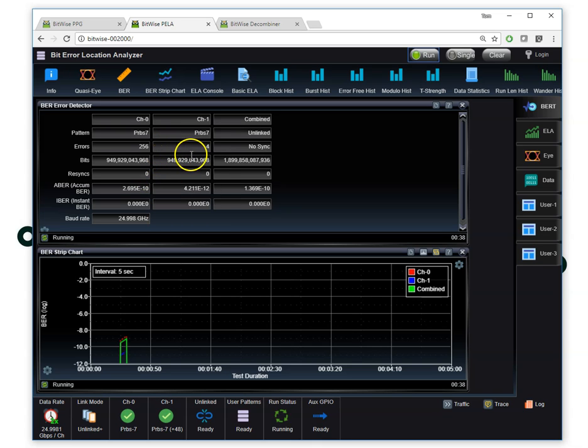It's interesting that my error injector was set to inject 64-bit errors on one lane and single-bit errors on the other, and you can see I pushed it 4 times, and that's the detail of the error measurement I can get from counting. Later on, we'll see using those same kind of error injectors, but being able to understand the burst length probability, for example, of different sizes of errors. So let me go ahead and stop that analysis, and we'll move on.